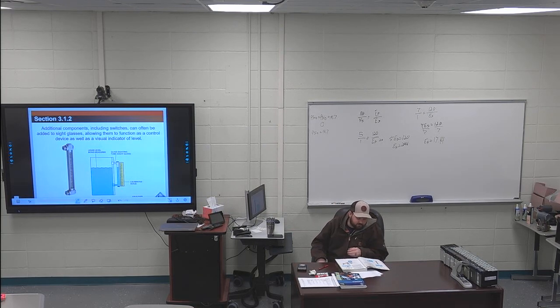The first 2 sentences on page 22 are an online test question. However, it is important to note that conditions inside the vessel can lead to inaccuracy. For example, when a steam boiler or burner is in operation, air bubbles form inside the boiler vessel, raising the level of water inside. So there can be some inaccuracies with doing this.